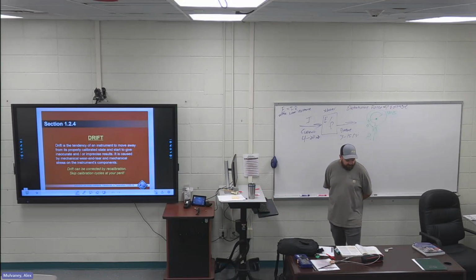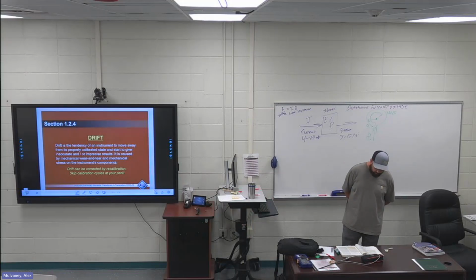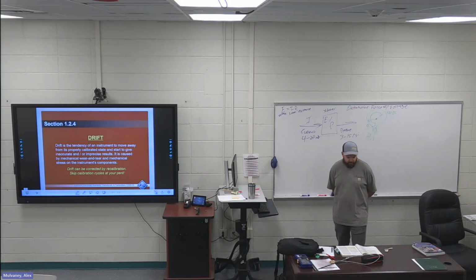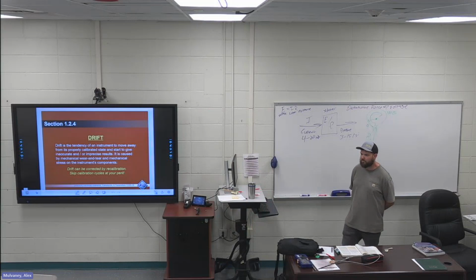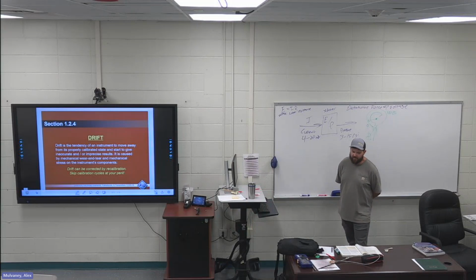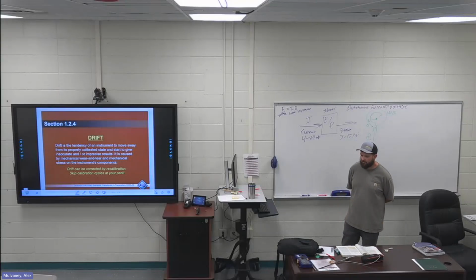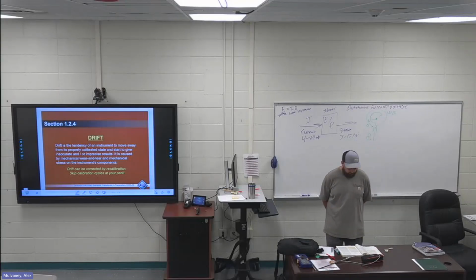Next paragraph, first sentence is highlighted. Drift is a gradual separation of the measured value from the calibrated value. You get that a lot with scales. A lot of times I would have to go calibrate a scale at least once a night or every other night. Capacitance scales really have a lot of drift, or at least the ones that I've been around.